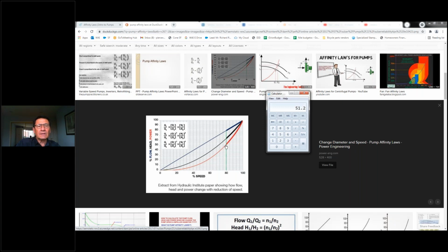What's more important is think about when you engineer a system and you choose the power rating of your drive, motor, and pump. You're going to oversize it just a little bit. Certainly there's some unanticipated consequences of the design, etc., so you give yourself some service factor.